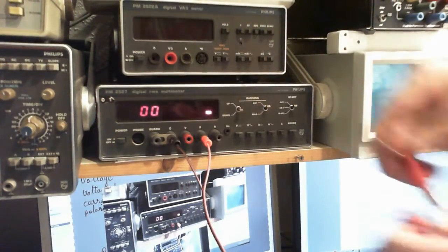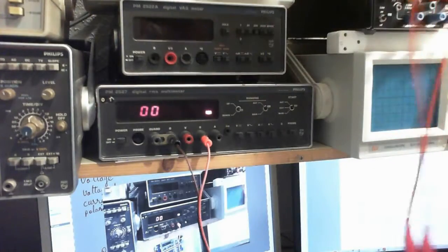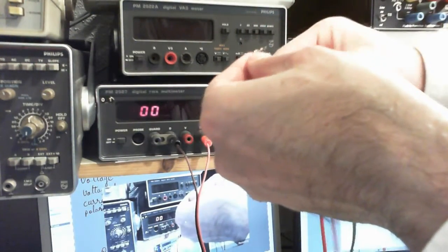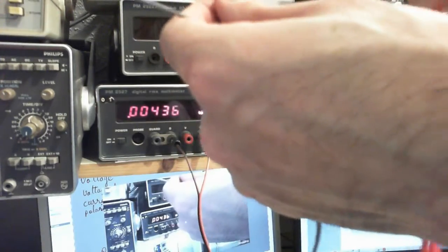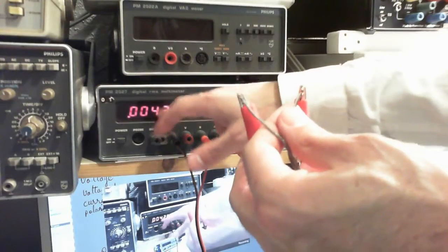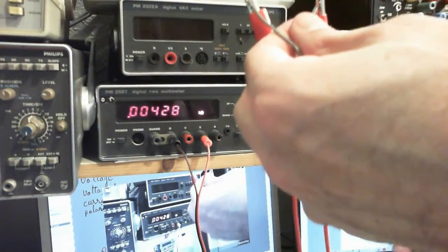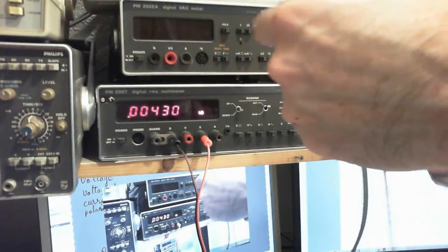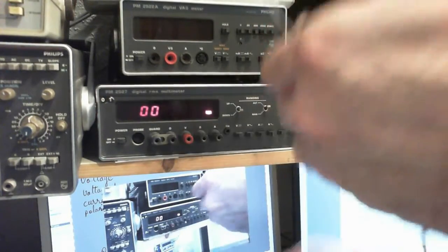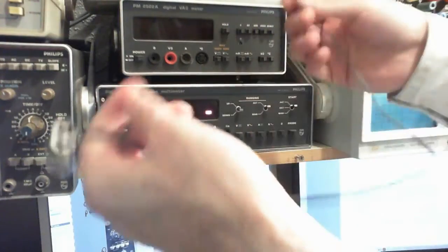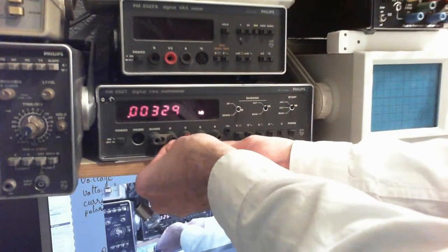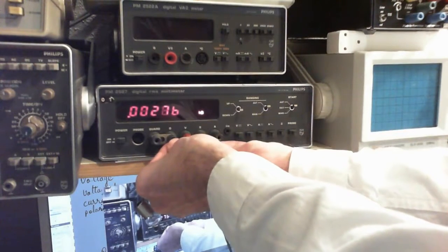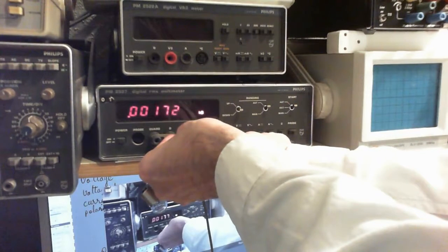I'll connect these alligator clips over here, and then I connect this over here. You see, as I'm connecting more wire to this probe, as the wire is getting longer, the resistance is increasing. Let me do something else. Let me actually measure the resistance without the lamp, just the probes. I go here and here, and the resistance is 0.0016.